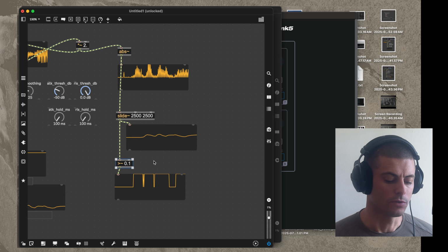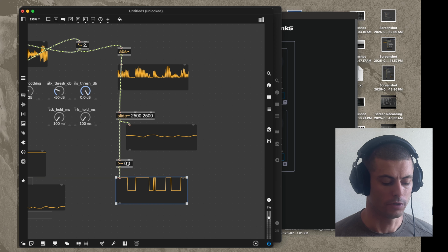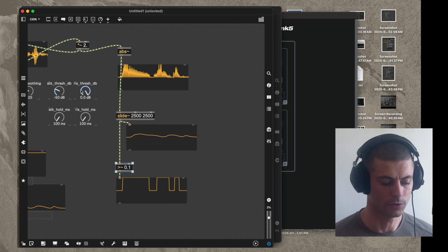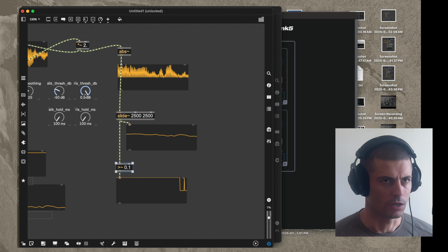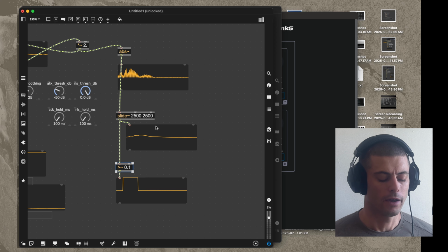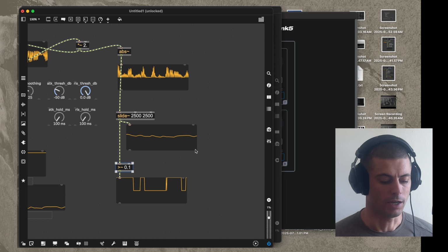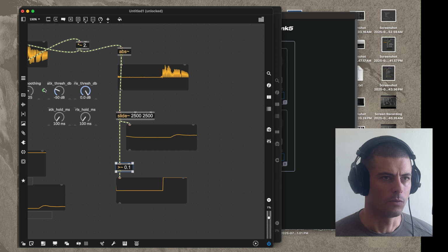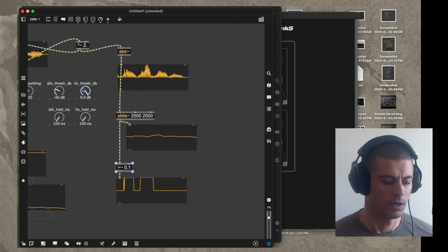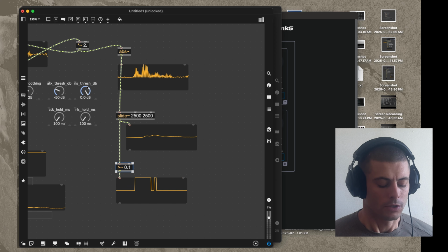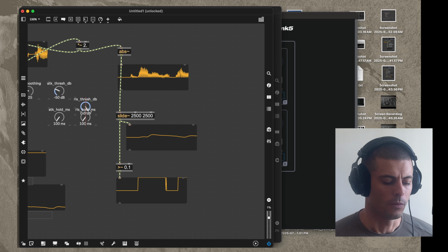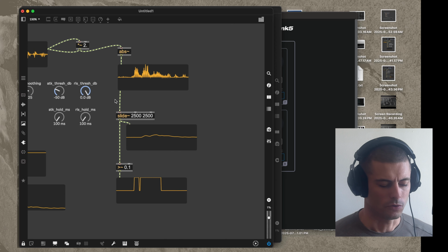So the first one is to use decibels, rather than a threshold on this amplitude value. The main reason is that it makes it easier for us as human beings to control the device, because the relationship between this actual amplitude and what we perceive as loudness is not linear. So when we think about it in decibels, we can just make it easier to control this.